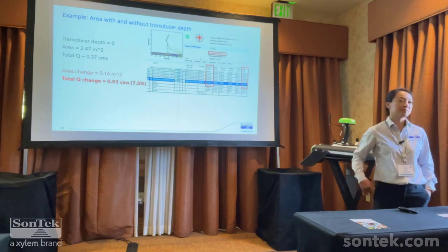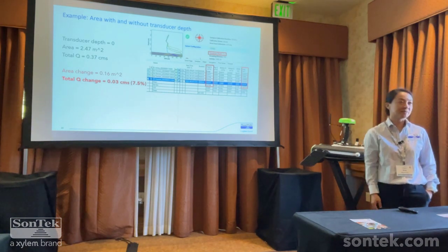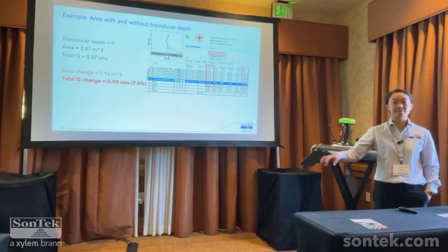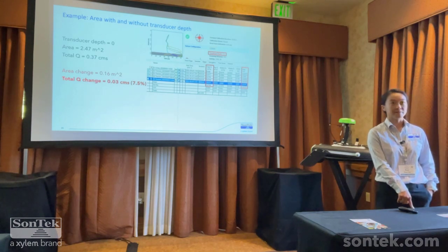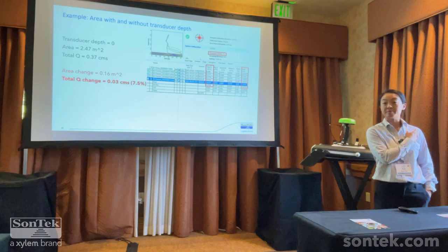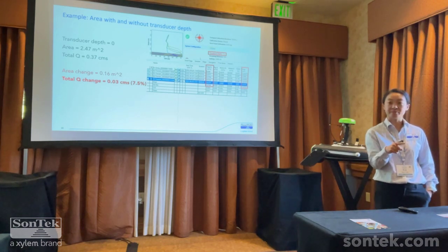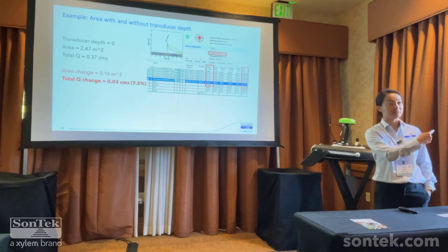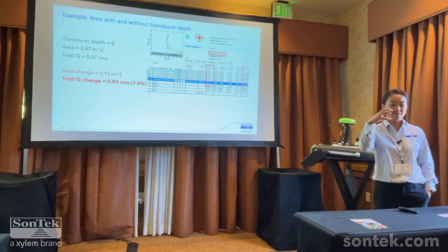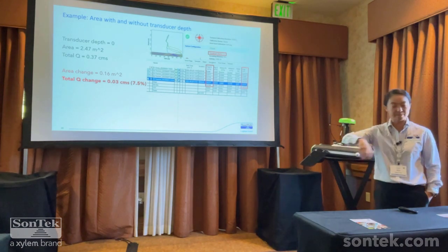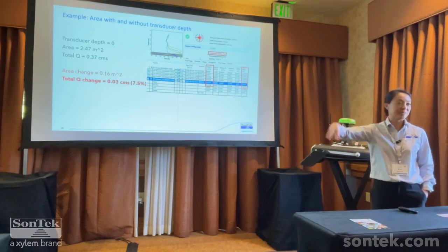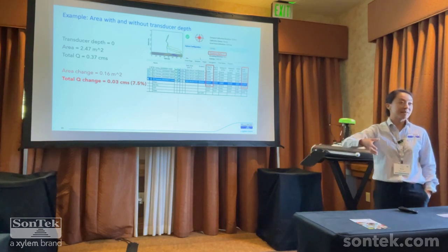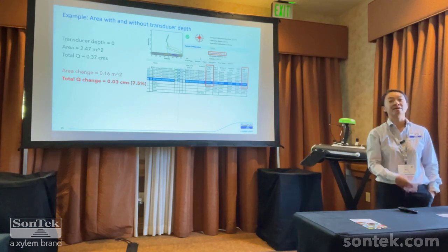But in general, if the boat's moving around or squirreling around, that's okay. The bottom track or the GPS will take care of it. This afternoon, we are planning to do some tests at the swinging bridge. If you're on a field trip, you might be passing our site. We were there yesterday, and there are some boils just downstream of the bridge that bring the instrument towards the bridge, almost underneath it. So the transect just looks like this big snaky pattern. But that's okay. The math takes care of it, and the GPS and the bottom track will take care of all of that for you.